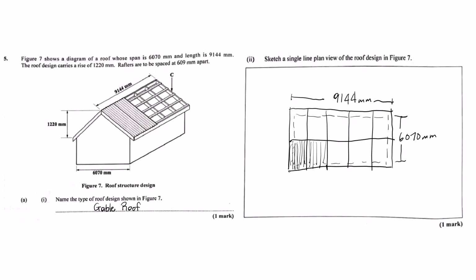So what are the key structural members holding this specific roof up? We hear about rafters. Absolutely. Rafters are, you could say, the backbone. In this design, they're spaced 609 millimeters apart. They're the main diagonal support. They run from the ridge down to the top of the walls. But they don't work in isolation, do they? No, definitely not. There were other crucial members tying it all together. The sources point out four other key ones for this kind of roof. All right, let's break those down. What else is essential up there?